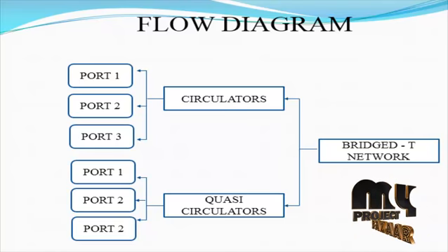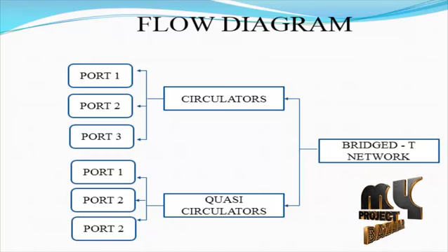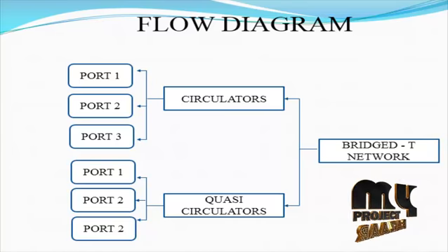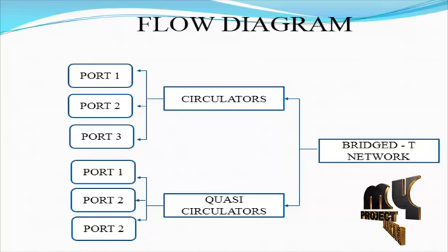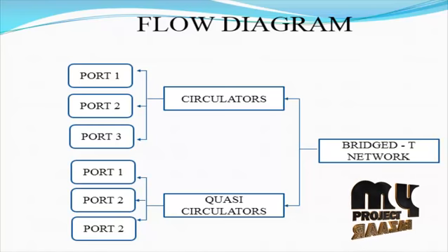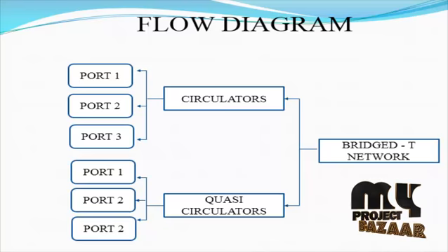The signals from port 1 to port K can be expressed by combining the clockwise and counterclockwise signal flows. It is practical to design a 3-port circulator using the 3 QCs based on the type 2 BTN topology. It is predictable that the circulator using type 2 BTNs will result in high power consumption and increase the circuit complexity due to the external amplifiers.